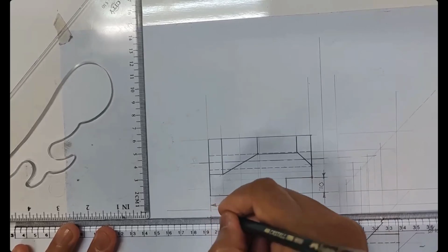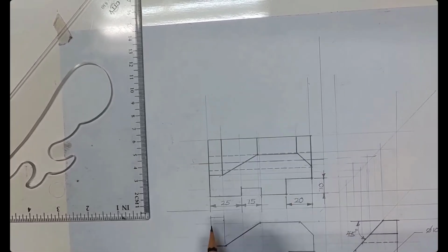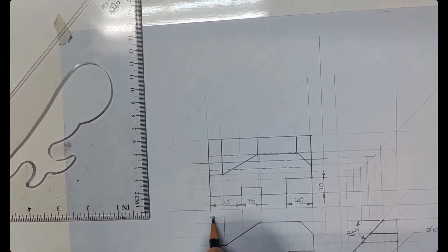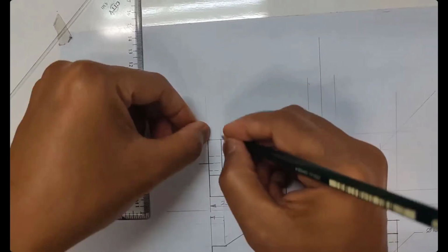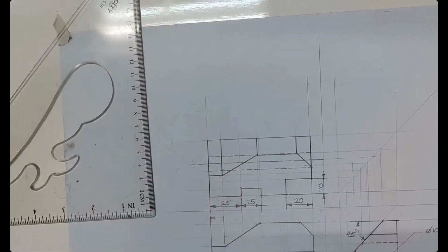So this one will be 10 units, instead of you doing it at the top view, because the reader needs to know the dimension of the chamfer, and the view that shows the chamfer clearly is the front view. So put the dimension on the front. If you put 10 on the top view, it's a little bit not facilitating the reader. Understand me? Then you will know, oh, the chamfer dimension is 10 from here, 10 from here.